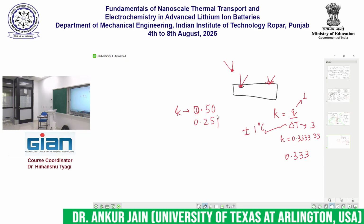If you go back, purchase more expensive thermocouples which are accurate up to 0.1 degrees Celsius, then your thermal conductivity will be between 1 over 2.9 and 1 over 3.1. Correct? I don't know what these numbers turn out to be, but this is much tighter now, right? And you should be confident of reporting thermal conductivity to the second or the third decimal. In fact, there is a whole field called uncertainty analysis, which I will not go into in this short course.